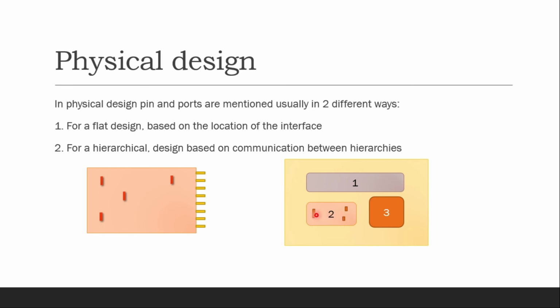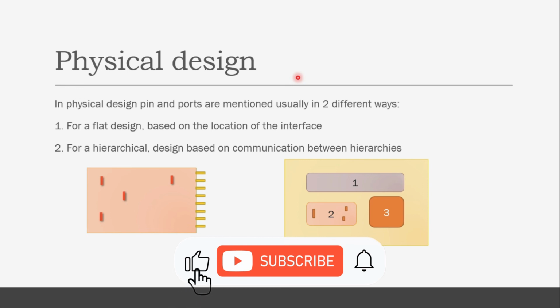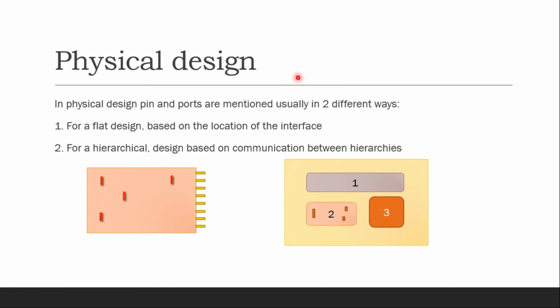For him, what are the ports? The pins that he will expose to the top layer. This is some kind of an abstraction, used as an abstraction to the top level. So you may say I have designed a block and I have given ports to my full chip, and the full chip people will say, okay, these are the pins of the device. I hope you got some idea about what a pin, a port and an interface are, and how they are called differently in different fields and design levels.